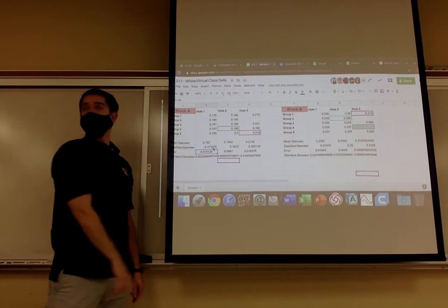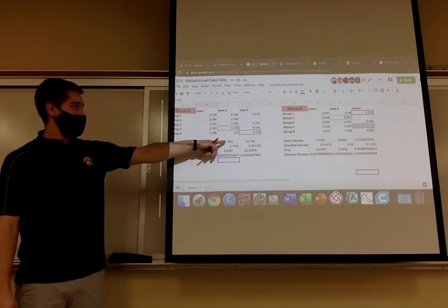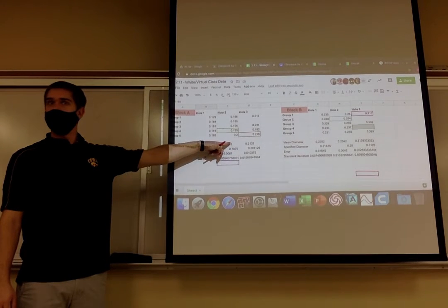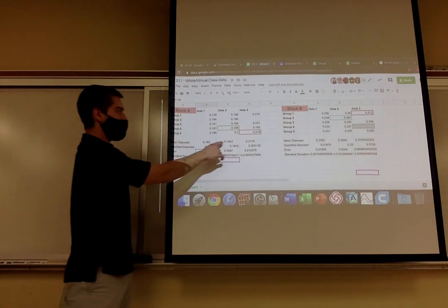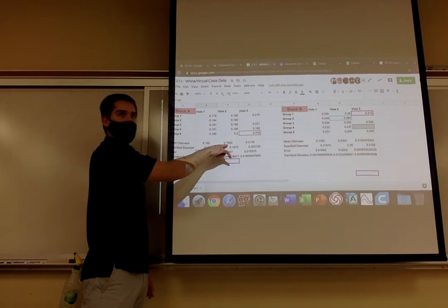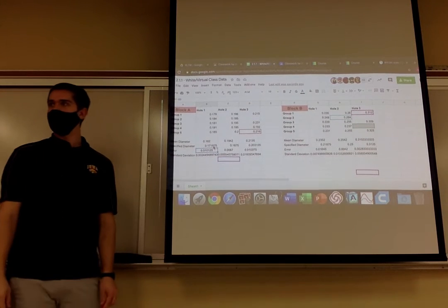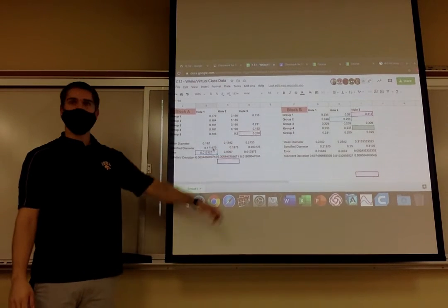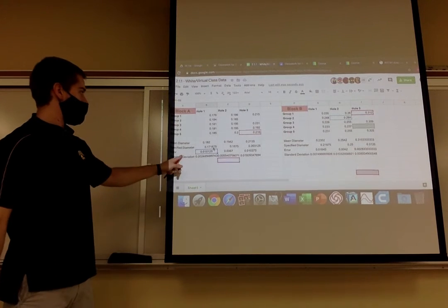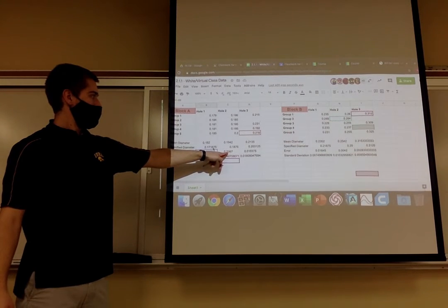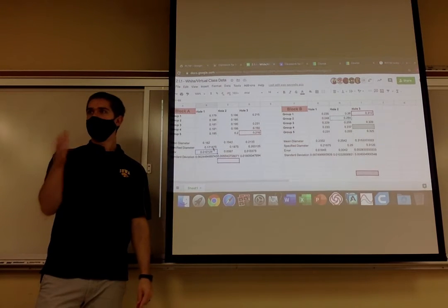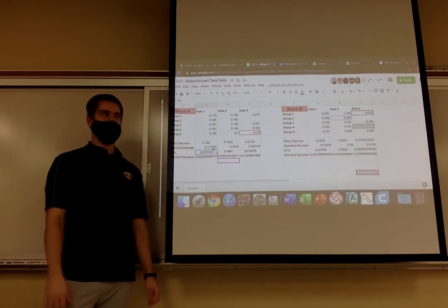We actually measured the hole diameter. Is it exactly what I designed it to be? No. I took an average of all of our measurements and said, we got a 0.19 inch hole instead of 0.1875. I list the error, which is how far off my measurement was from the specified diameter.